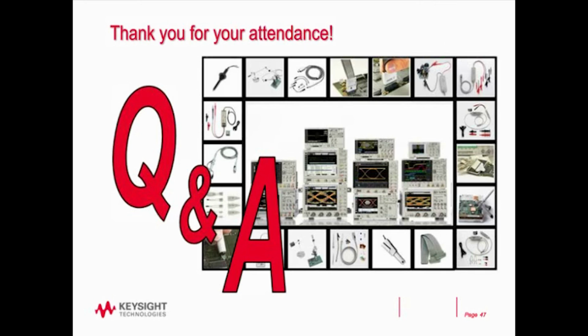Perhaps in the future we may enhance the product to include this new power rail probe for that particular measurement. Okay. We're running a little over here, so this will be the last question. What bandwidth scope is required for switching power supply measurements? My advice here, well, first of all, switching rates are getting faster. So the slew rates of many of your power devices are getting faster and faster, which requires higher bandwidth, and it's a challenge for all scope vendors to keep up with those requirements.